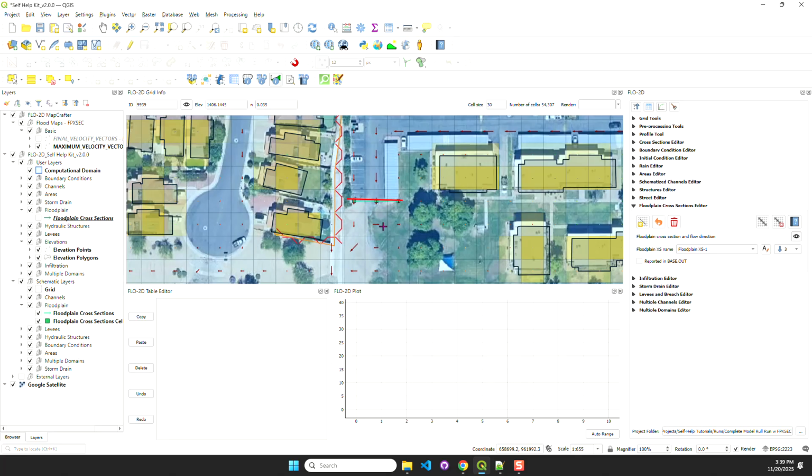This one, you can see if I were to move this one south by 1 grid element, that would be an invalid cross section because the flow is not crossing the line. It would then be parallel to the line. So that's rule number 2. The flow must cross the line. It doesn't have to cross perfectly perpendicular to the line, but it must cross the line.